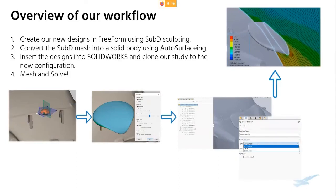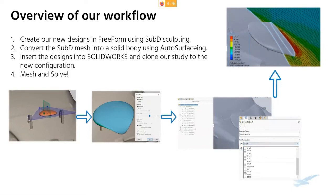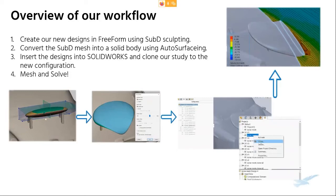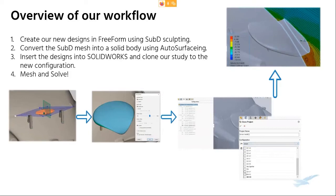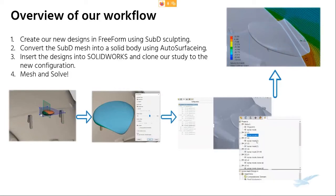We take that solid, insert it into SolidWorks itself as a configuration, and then we cloned our study to that new configuration in our Flow Sim. And then we just had to mesh and solve it in a batch mesh. So it's kind of 4 steps, and it really is that simple. In fact, it's actually like just 3 button clicks with the importing in and cloning the simulation itself. So it's a very straightforward process.